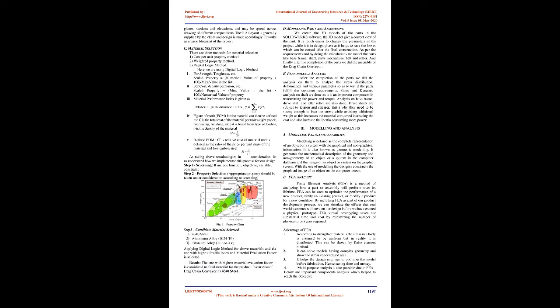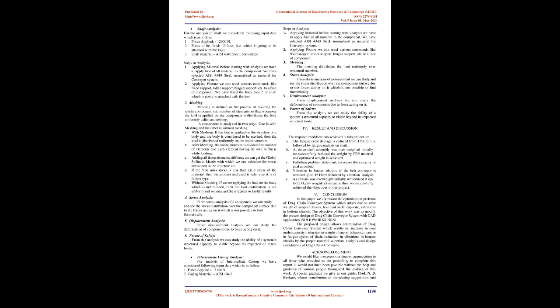Performance analysis. After the completion of the parts, we did the analysis on them to analyze the stress distribution, deformation, and various parameters, so as to test if the parts fulfill the customer requirements. Static and dynamic analysis on the shaft are done as it is an important component in transmitting the power and torque. Analysis on the base frame, drive shaft, and idler roller are also done. Drive shafts are subject to torsion and stresses. That's why they need to be strong enough to bear the stress while avoiding additional weight, as this increases the material consumed, increasing the cost, and also increases the inertia, consuming more power.